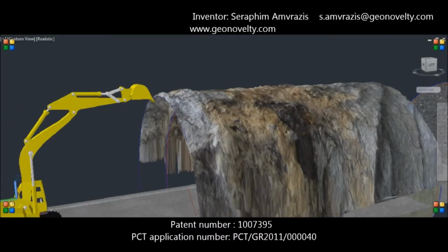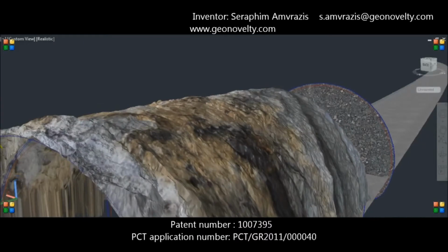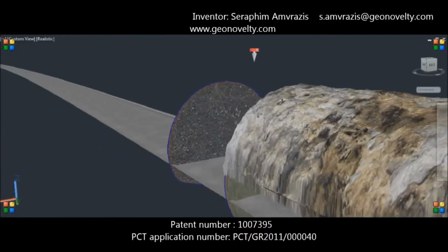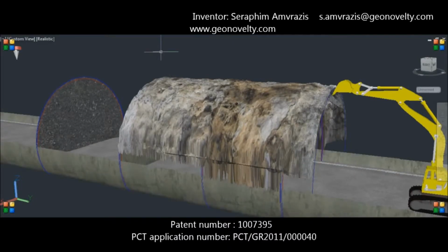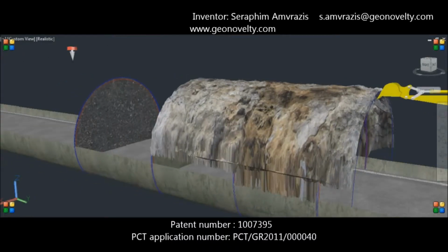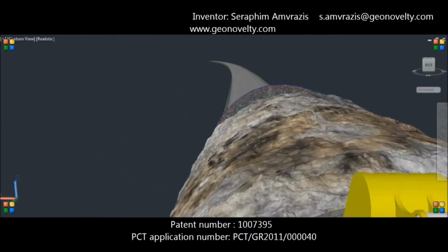Generally, the excavation behavior for each particular soil is an unsolved issue that concerns many tunnel engineers. Every 10 centimeters of overbreak may increase the excavation cost by more than €1 million per kilometer. The domino effect that may come from bad excavation prediction follows the project until the end.